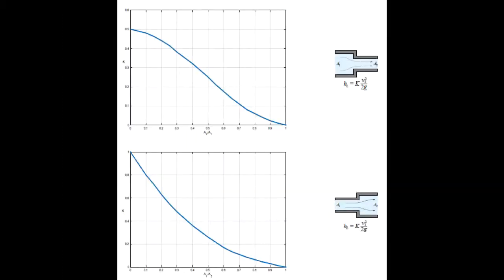The next figure, 12.5, gives minor loss coefficients for contractions or expansions of pipes. So going from one diameter pipe to another, you get some loss associated with that. Contractions are on the top, expansions on the bottom, as a function of area, so how big of a contraction or expansion you go through. And be careful with this figure because there are two different velocities, one on the left side, one on the right side, and the one to use is very important for these graphs.